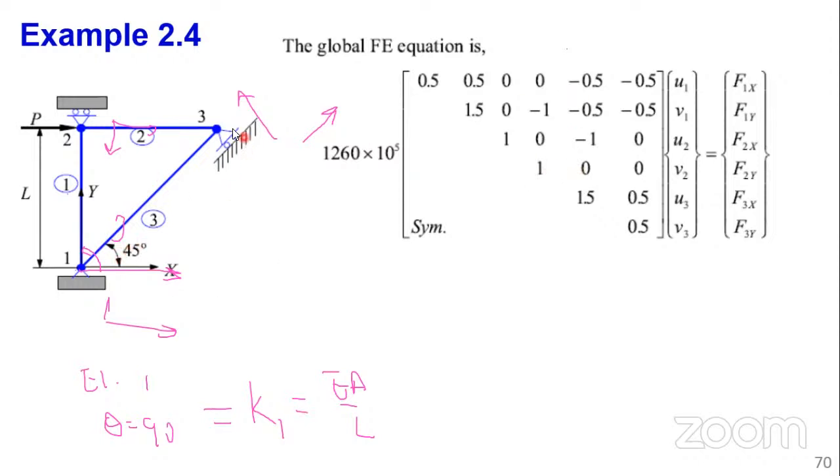Once you determine, like now K2 here, the horizontal direction is that. But we are talking of node 2, 3. So theta 2 for element 2 is equals to 0. Theta 2 is equals to 0. So you can go ahead and get the direction cosines and get what is K2. For K3, element 3, we move from the row node I, J, 1, 3. So theta from the horizontal axis is equals to 45.